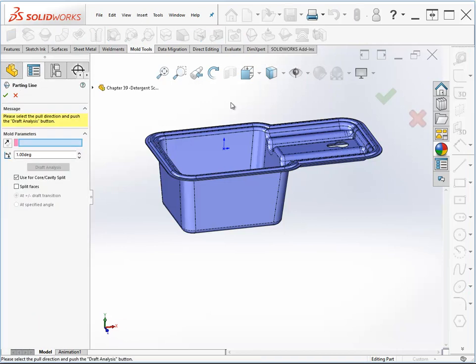I should note that whenever you're designing a mold, you need to do one of several things. You need to actually be the guy that's going to build the mold, or have a lot of experience doing this, or be working directly with one of the other two guys who's either designing the rest of the mold or building the rest of the mold. Plus, be aware that what SolidWorks does is not mold design at all. The mold tool's name is kind of a misnomer because really all we're doing is creating the cavity and core blocks that are very often created as inserts that go into a mold die.